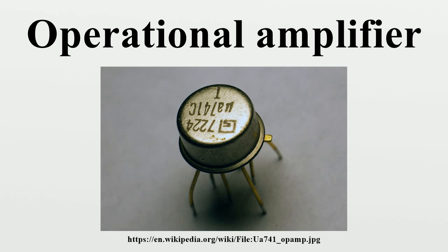Closed loop. If predictable operation is desired, negative feedback is used, by applying a portion of the output voltage to the inverting input. The closed-loop feedback greatly reduces the gain of the circuit. When negative feedback is used, the circuit's overall gain and response becomes determined mostly by the feedback network, rather than by the op-amp characteristics. If the feedback network is made of components with values small relative to the op-amp's input impedance, the value of the op-amp's open-loop response A_OL does not seriously affect the circuit's performance.